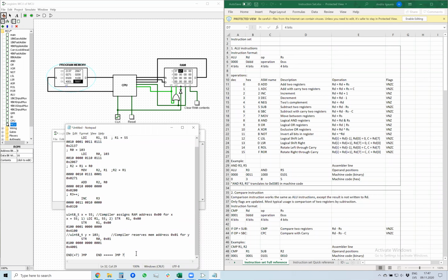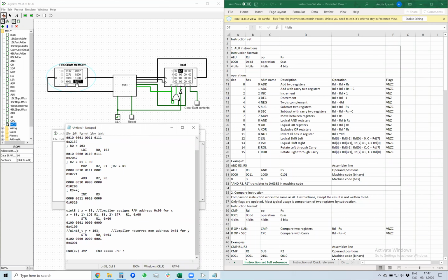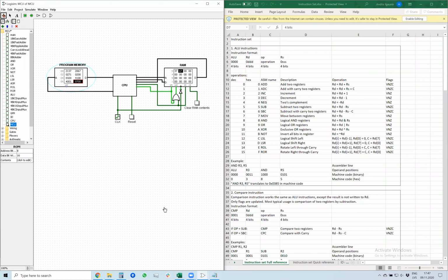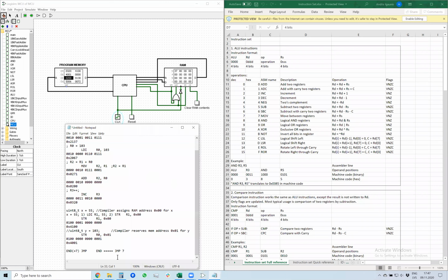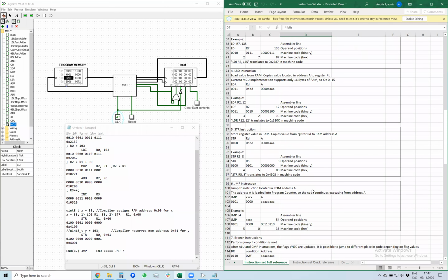So we will just translate this into assembly, because I'll give you an example. For example, this flash memory location would be initialized to 0, 0. So if we do the clock, you see that some old code is executed and something weird starts to happen to our code. You see our RAM contents are being overwritten with this old code, which is not erased. We don't want that to happen, so we need to add this end, jump, end line at the end, which we will translate.